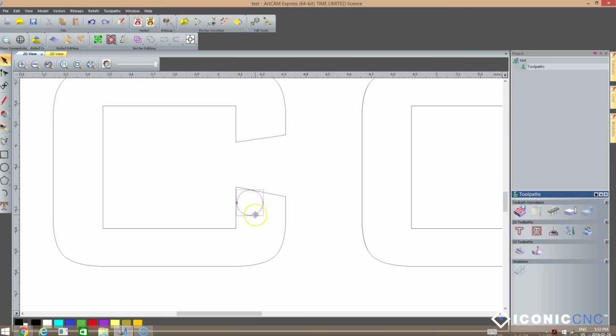What the V-bit carving toolpath does is it basically recognizes the square corners and the geometric corners in an object, and it will machine them out. And essentially what would happen, if I could turn this on an angled view, you'd see the tool swoop out of the material and then swoop back in. And as it does so, and it uses V-bits to do this, the V-bit will create the square corner. It is the only toolpath that has the ability to create square geometry.